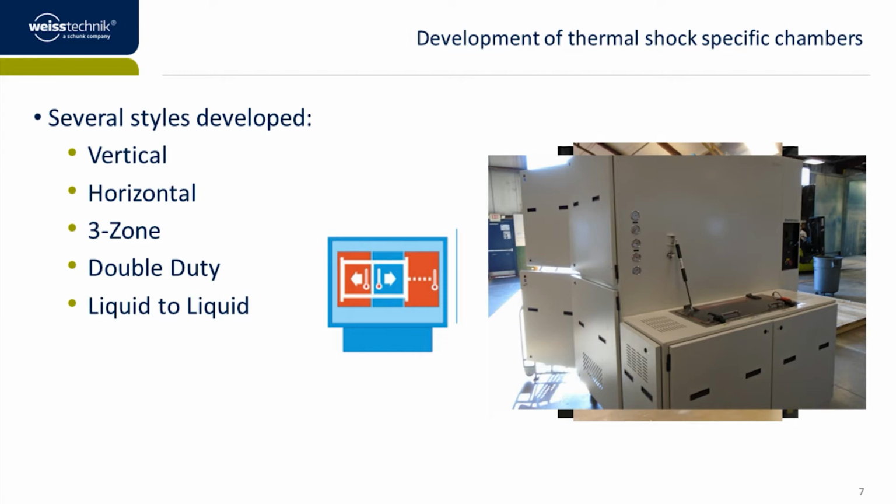Now, a 3-zone is a little bit more rare of a test chamber, but we still offer them. And this specific type of chamber is designed for those who are still following the original thermal shock test, where products would move from one zone to another in a manual fashion. So what this is, the cold zone on the left is in blue here, and that is fixed. It doesn't move. The entire hot zone, the right window you see, that whole zone moves independent of the basket. So it can move left to right.